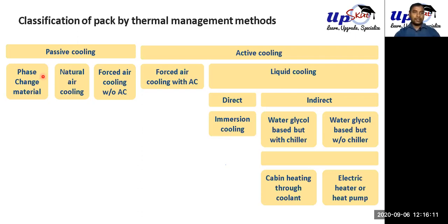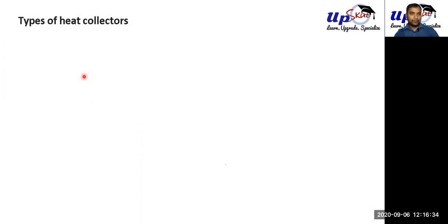The air cooling is only for the cheapest of the cars. That is, for electric, it is the Nissan Leaf. So for a very cheap car, this works. For a very small battery, for a very small motor, for a car that is never going to be pushed. So everyone else is using the liquid based cooling, the water based cooling.